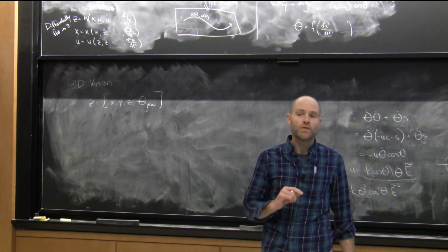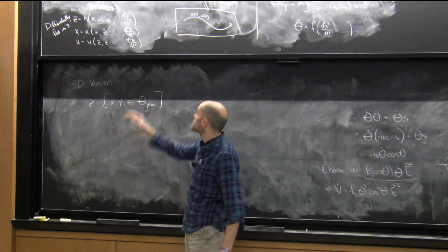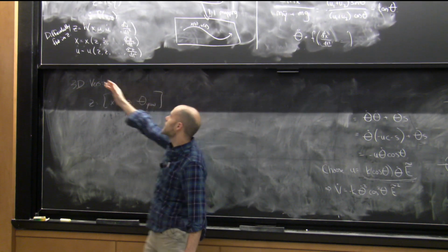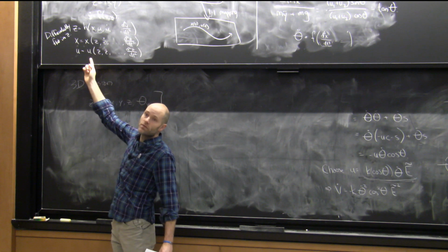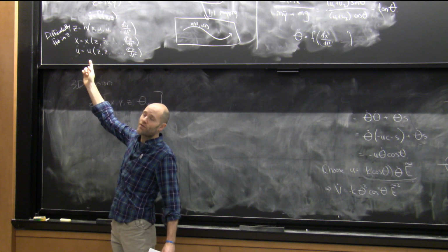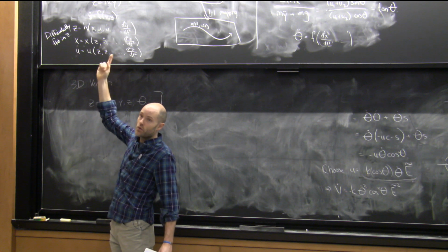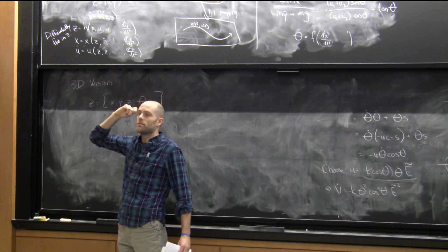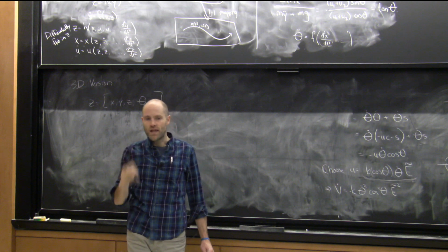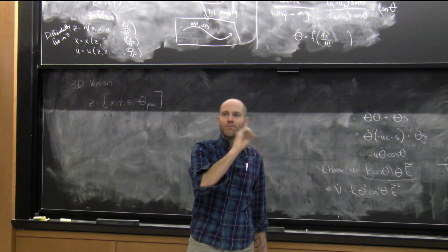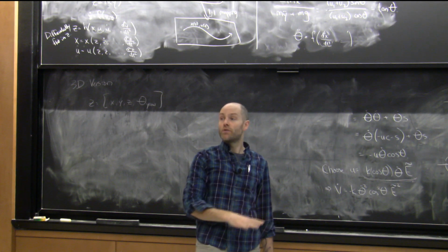In general, the tools for differential flatness are less developed. There aren't algorithms that people know or talk about that say, given some h, how can you check that there's some way to write it down. There's still a manual step of running through the algebra and finding the recipe for backing out x and u as a function of the derivatives. I don't know of a numerical recipe for checking the flatness property of a given system. Instead, when somebody figures it out, they write the paper, and now it's in the tome of knowledge and people use it, which is how nonlinear control used to be more generally.